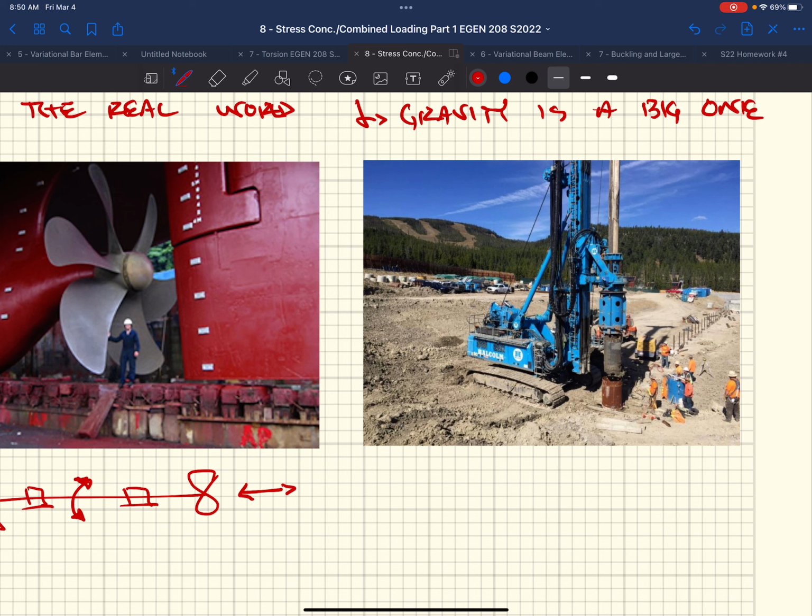There's a huge building up there, like nine stories, a huge lodge, brand new. It's one of the largest buildings in the Northwest, so check it out. Massive. They realized when they first started building it that the building weight was pushing it down the mountain. So what do they do? They go up there and drill a bunch of holes, fill them with rebar and concrete, and tie back the mountain. There's a series of these drilled caissons, drilled piers, in a ring in this valley between these mountains, that essentially tie back the mountain and keep this building from going down.